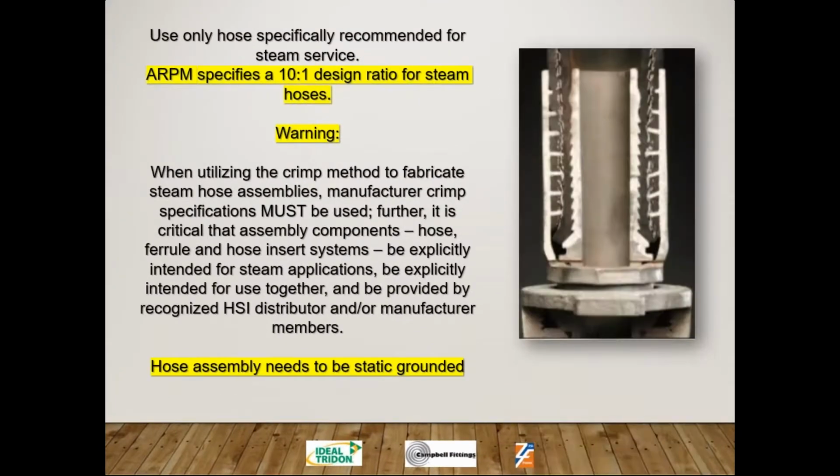When it comes to steam, it needs a 10-to-1 safety factor. Also, all hoses need to be statically grounded, but steam can get very dangerous when it acquires a charge, very dangerous to the operator. And the way the Campbell steam fitting is designed, if you notice the little teeth on either side of that, they will bite to the wire of that steam hose, and that steam hose is electrically conductive as soon as it was crimped.